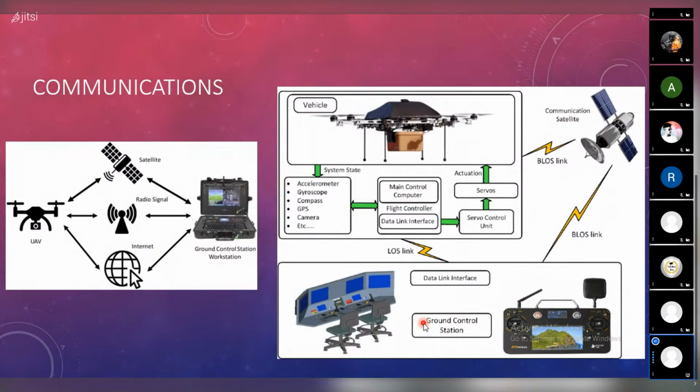Beyond that range, if you want to operate the drone, you need a more sophisticated communication system. In general, you can do that with internet or IoT based systems, or like the defense sector, which uses satellites to do the same. In areas where internet connectivity is not available and you are not able to connect with your system, satellite communication is also used. So this is the base for how you go about selecting which communication system you need. If you are making a hobby drone or a racing drone, you will not go for satellite communication, that is out of the question. You will go for a communication system that uses Bluetooth or radio waves of other frequencies. So that is about the communication system.